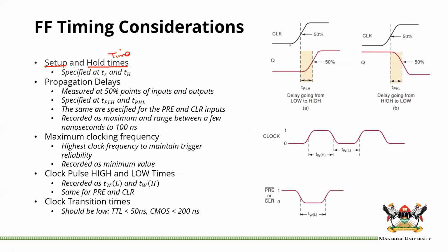You can see you have a clock signal and your output. When you give the clock signal, the idea is that your inputs would have gone in before. Those are your inputs, say J and K, and this would be your setup time. When you give the clock transition, the clock is active the moment it goes through the 50% point. Your output was still 0, and you're trying to change it to 1. You're trying to set it.